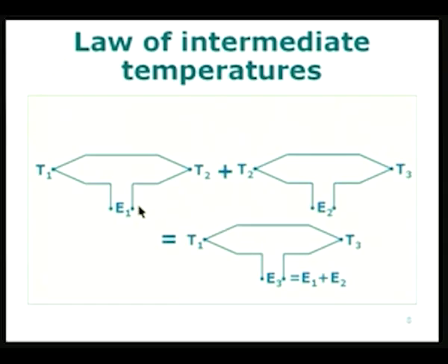Actually, what I should do is add this E1 and E2 to find out what is the output of this thermocouple if this were at the measuring junction temperature and this were the ice point. Therefore, to find out what is the correct temperature, all I have to do is to add whatever is going to be obtained by this arrangement between the room temperature and the ice point.